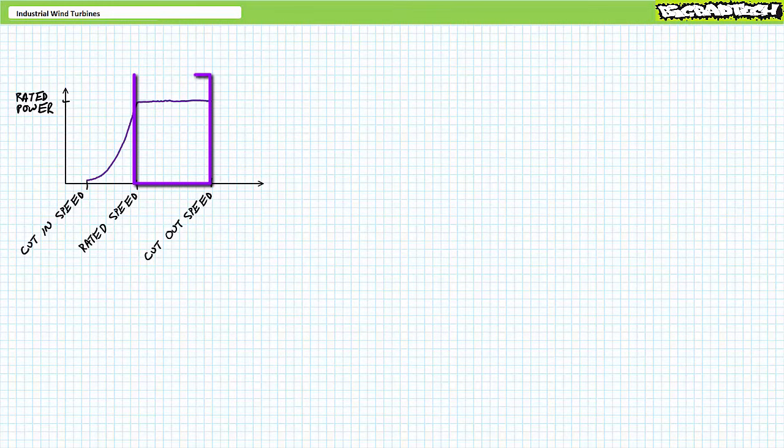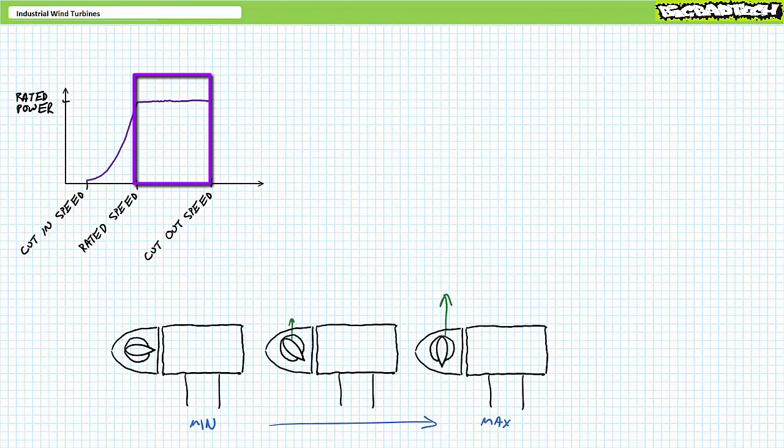This manifests itself as the turbine flat-lining output at the nameplate rating at speeds above the rated and below the cutout speed. One of the principal means of limiting mechanical power input is by pitching the blades such that they progressively shed more and more input wind.